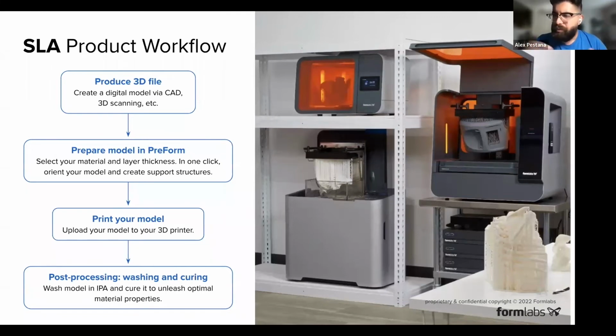It really depends on the part you're choosing and if there's any concerns about it being too difficult to remove supports after it's cured, because we're a single material process, the supports are as strong as the rest of the model. So we've done a lot of work on touch point design and things like that to make it as easy as possible, but some customers still will take them off before they cure. So it really depends on what you'd like to do. But wash the parts and then cure the parts. We have dedicated solutions for Form 3. We have the same for Form 3L.